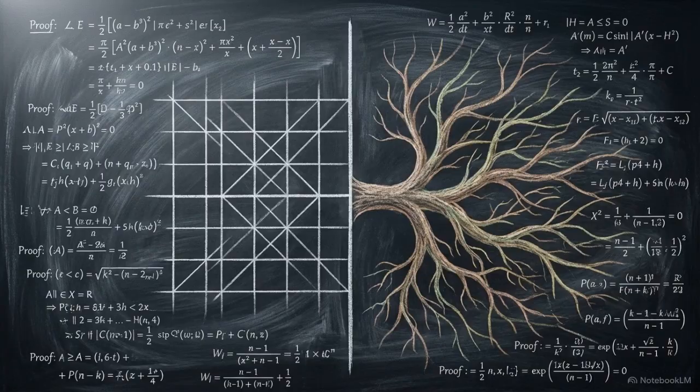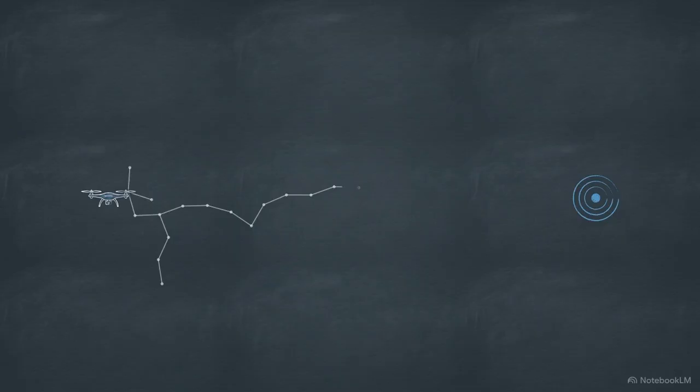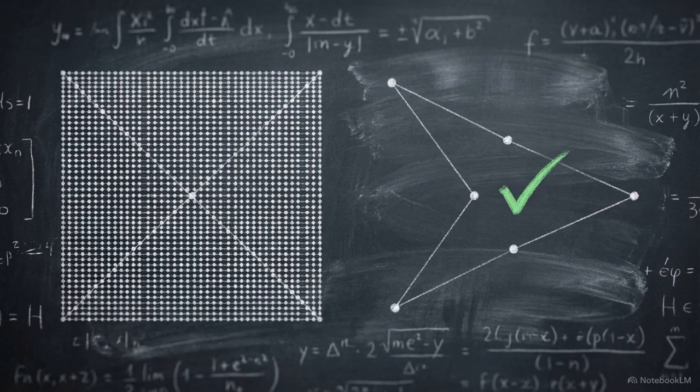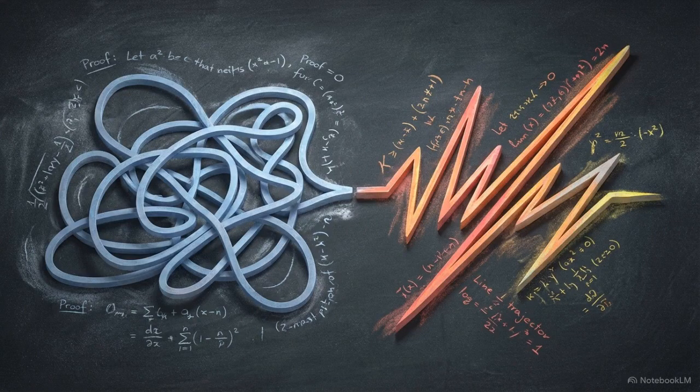One solution is to deploy stochastic heuristics, including sampling-based methods like rapidly exploring random trees, or RRTs, and bio-inspired models. RRTs are algorithms that quickly search high-dimensional spaces by randomly building a space-filling tree toward unexplored areas. These methods trade absolute mathematical perfection for feasible compute convergence. The first branch of stochastic planners is evolutionary optimizers, specifically genetic algorithms and differential evolution.